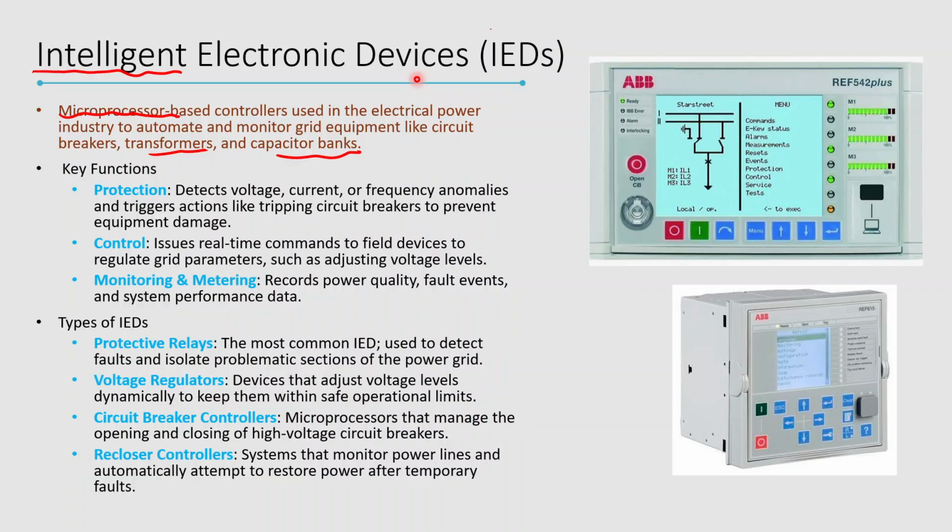It also produces control functions, issuing real-time commands to the field devices to regulate the grid parameters, such as adjusting voltage by changing the transformer taps. And it also facilitates monitoring and metering, which records the power quality, fault events, and system performance data.